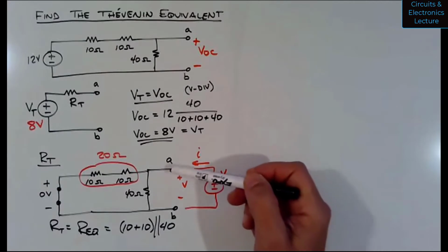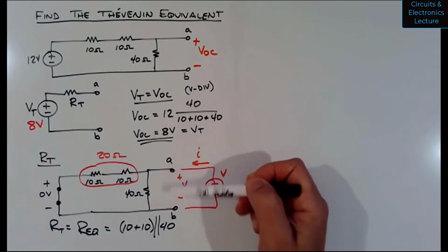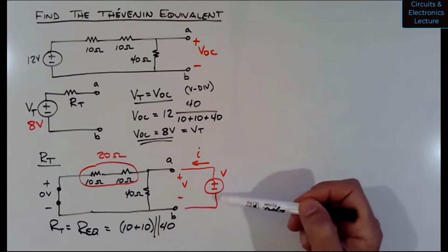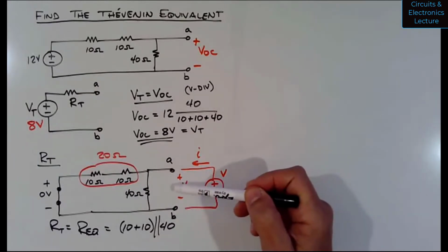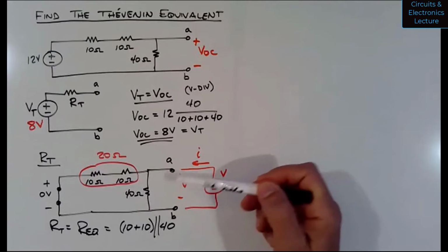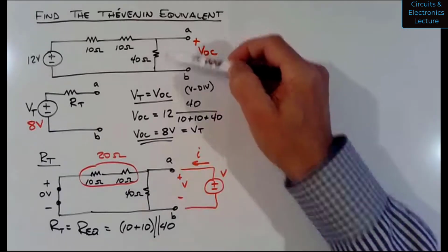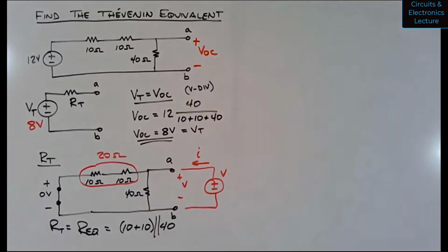Now, I want to find the equivalent resistance between A and B. So it's as if I'm applying a source to get a voltage across those terminals, determining the current, and when that current I flows, now that current splits between 40 and these two 10 ohm resistors. They are no longer in series, right? This up top is a different circuit than this circuit at the bottom, okay?